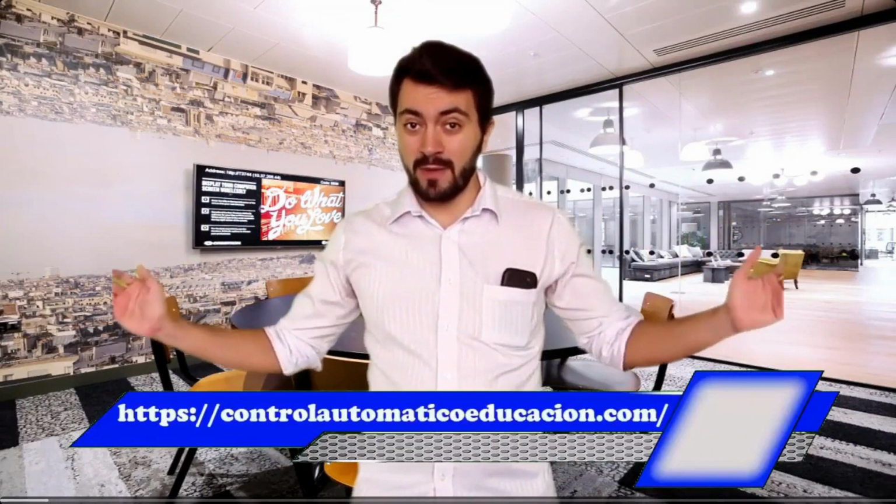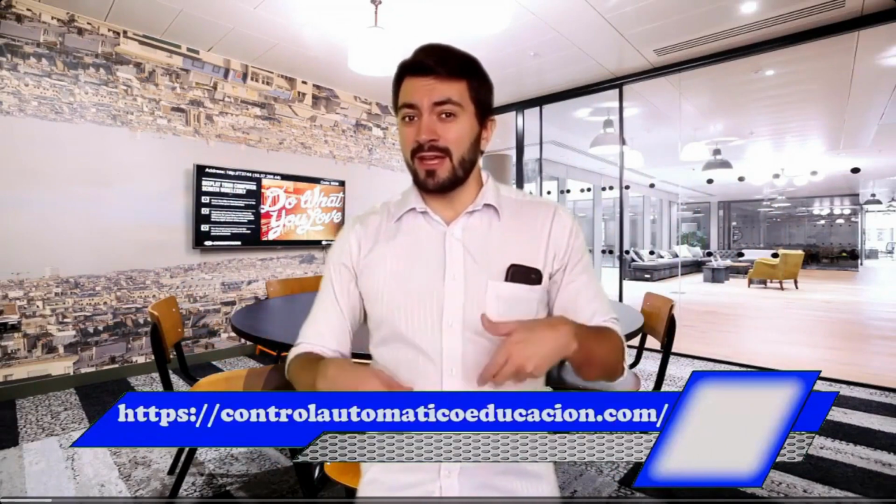In today's video, we're going to learn how MATLAB displays different types of number notation. We are going to learn how to use scientific notation, look at formats for large numbers, long, formats for small numbers, short, and we'll see what other options MATLAB offers us for displaying numerical results. So let's get started with today's video.